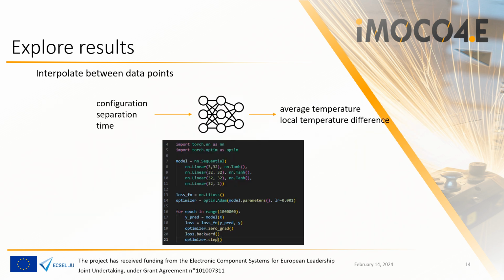To analyze the results, we use a neural network to describe the response surface, providing a quick and smooth evaluation between simulated data points. While linear interpolation could achieve this, a neural network is chosen to showcase its capabilities. Neural networks are effective in modeling intricate and nonlinear response surfaces, making them suitable for complex relationships or numerous input factors. However, the choice should consider trade-offs, as neural networks have challenges like interpretability and require careful tuning, whereas interpolation tables may be sufficient for simpler relationships and well-understood input spaces.